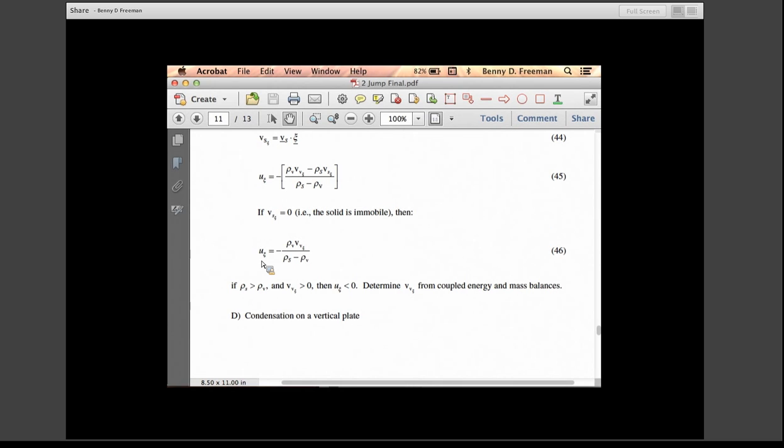Because the nitrogen only comes into that Stefan tube to replace any lowering of the liquid level. So for every millimeter of reduction of the liquid level in that Stefan tube problem, you've created a meter of gas that has to be moved out, just based on the density difference.